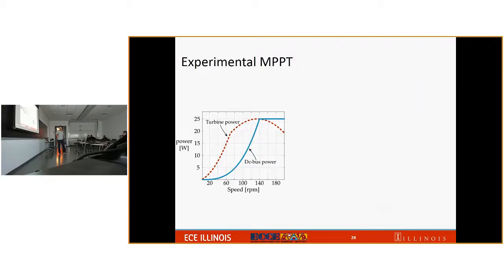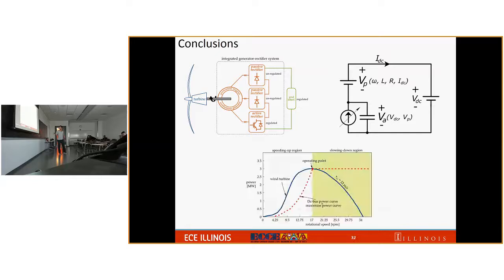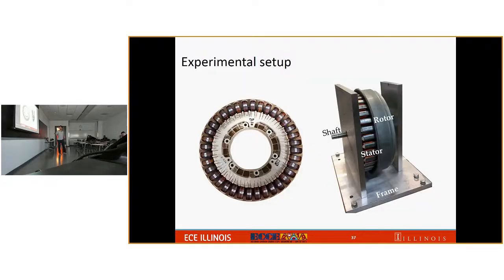But if you look into the stator structure of each motor, it has multiple teeth coming out, and on each tooth, it has a winding across each tooth. So in an actual generator design, we can make one group of teeth go to the passive rectifier and another group of teeth go to the active rectifier. That way we can integrate everything on a single generator. Yeah. That's more along the lines of what I thought you presented in the past.